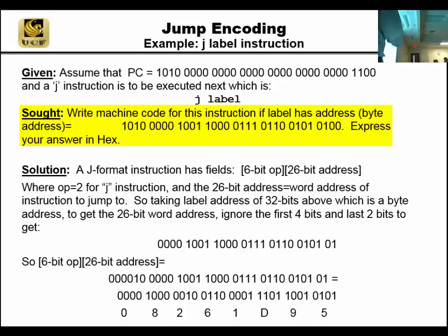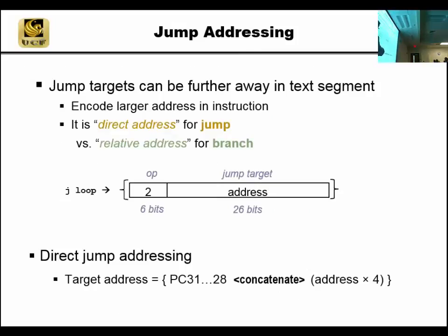So before we solve this problem, what is this? This is where we want to jump to, the address expressed in binary. Can I express this in hex? Yes, this is A, 0, 9, 8, 7. Where are we right now? Just to see, this is A, 0, 0, 0, 0, 0, 12, okay, C. So the question is, I'm asking you to write these bits. Those bits are the encoding of the jump instruction.